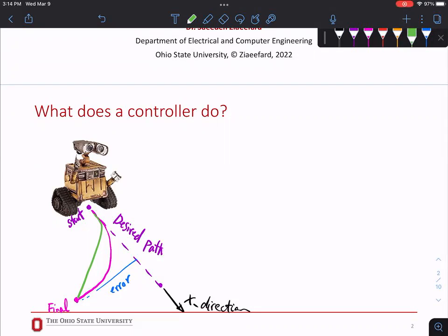The heading error usually happens with an autonomous robot, because the position control usually is based on the encoder of the wheel or on the IMU you're using. So all are sensors, and sensors have error. It's accumulated error. So this is a very quick drift off the path, like over 10 meters, 100 meters. When you start any wheeled robot, they will have this built-in accumulation of error. If it's not fixed, it will keep drifting off. We call it heading error.